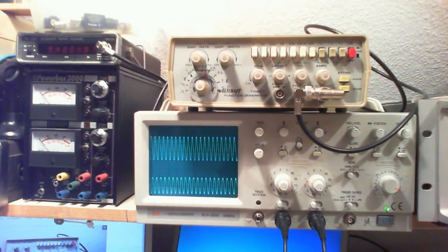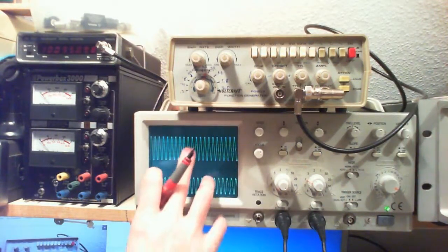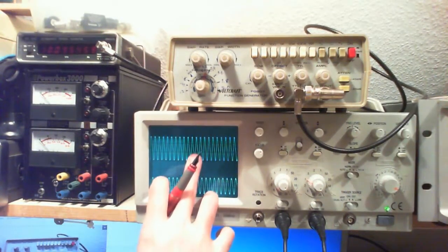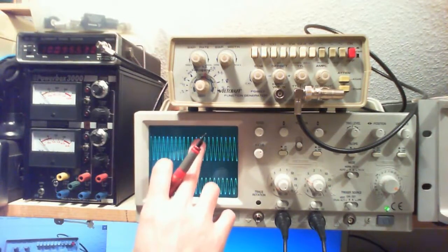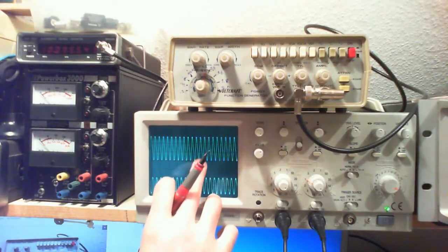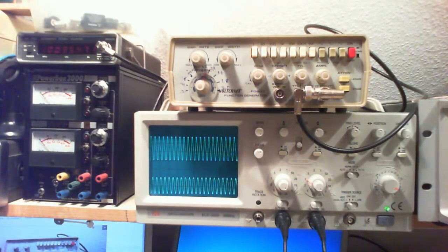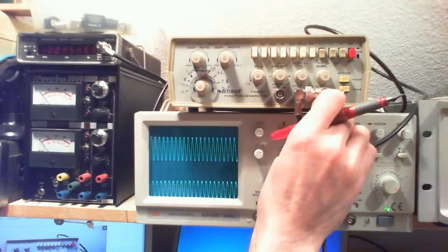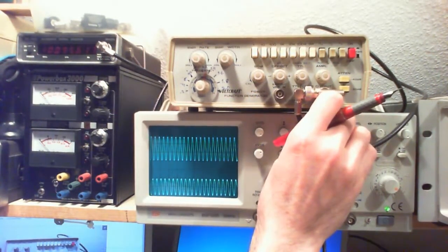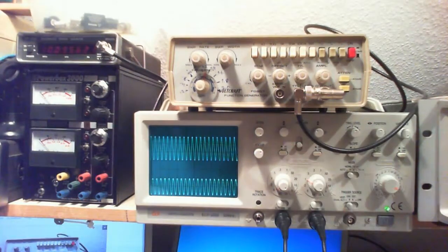And I can still keep going at, for example, 10.1 megahertz. I have 2.8 times 5 again, which is equal to 14 volts. My output is at about 1.9 times 1, which is 1.9 volts. So the input is 14 volts and the output is 1.9 volts at 10.1 megahertz.